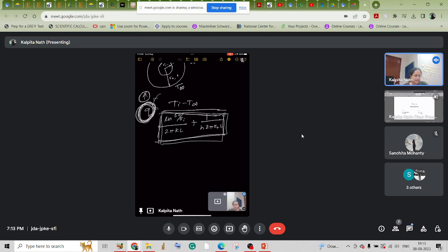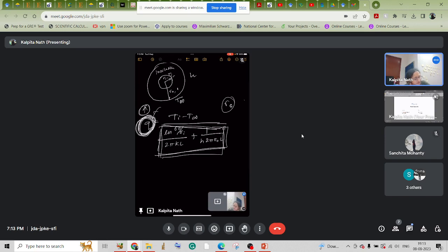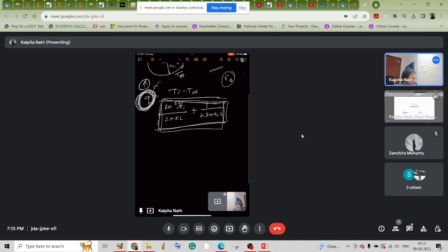And we don't want that. That is an unfavorable condition. So the point at which this heat transfer will be maximum, that radius will be termed the critical insulation radius, and the difference between the critical insulation radius and the inner radius will be the critical insulation thickness. Sir already told in the class that it will be found by dQ/dR0 equal to 0. If we do that, we'll find that the critical insulation radius is equal to K by H.